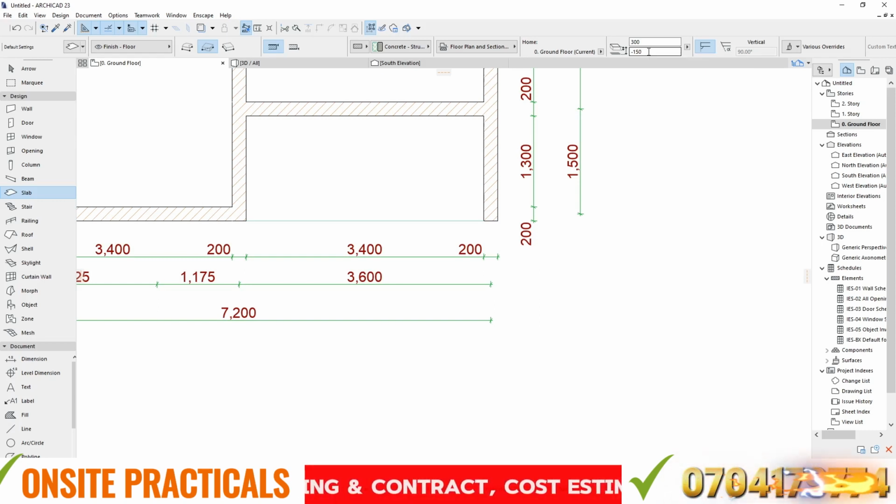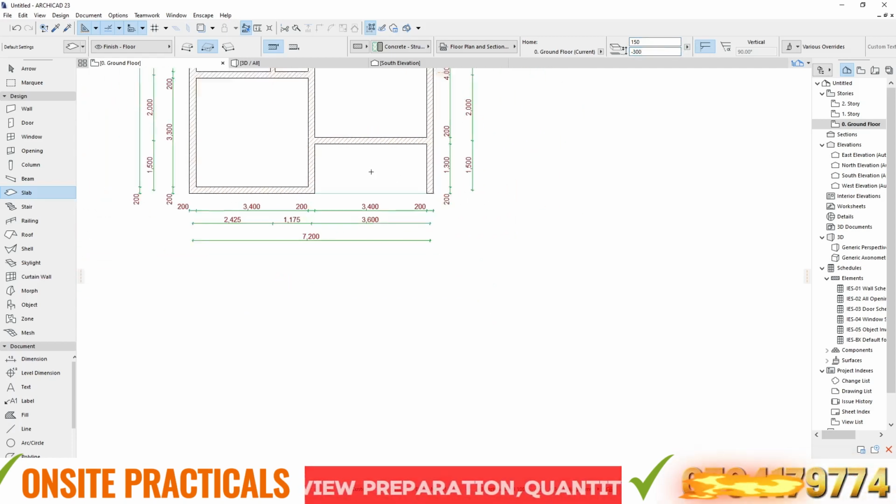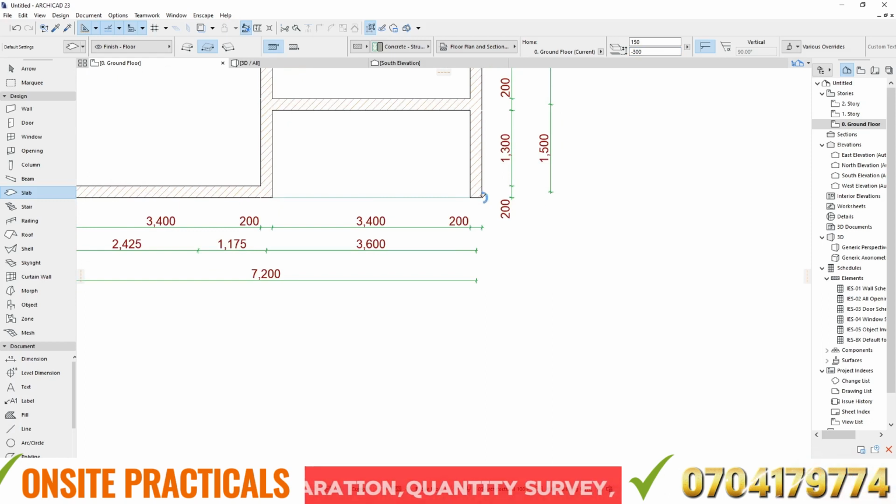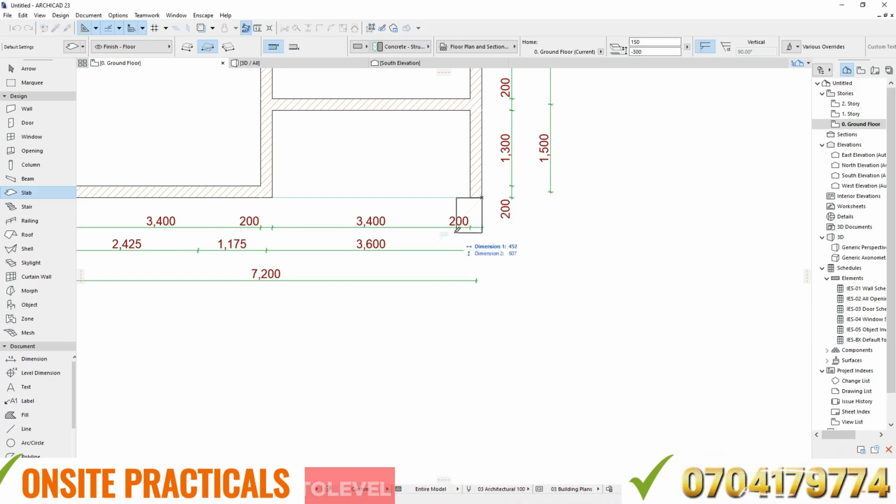So what I'm going to do here is say the next step will be 150. So here the height will be 150, but this one will be 300 because my steps are 150, or 6 inches. Once I have that, you see, cumulatively this one also will give you 450. So I can come here and draw that step again. I'm going to come all the way to there, and then I can decide what is the width. You see, I have 2 dimensions. I have 36, and then the other one which is changing.